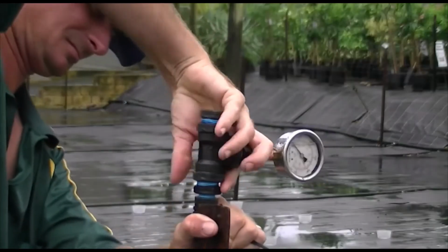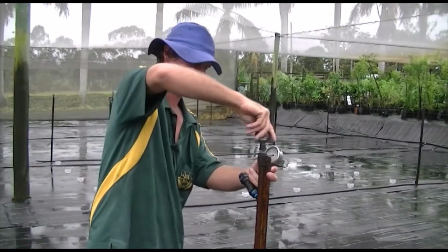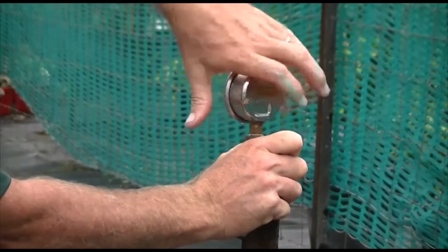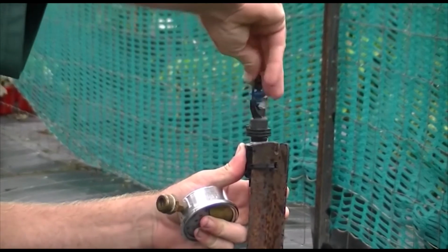The field evaluation is now complete and the test area can be returned to normal operation. Remove any pressure gauges and any Schrader valves that were used during the evaluation and return the irrigation controller to normal operation.